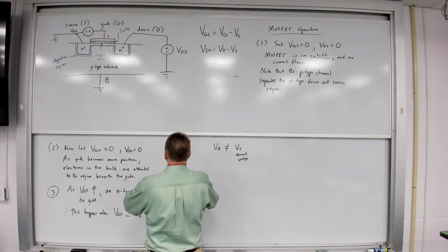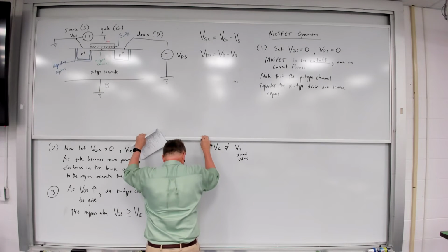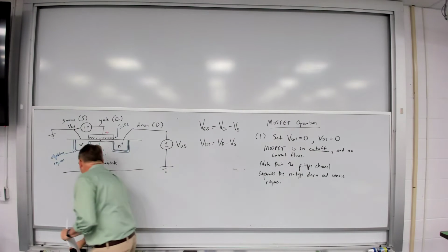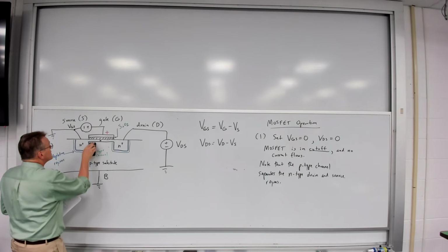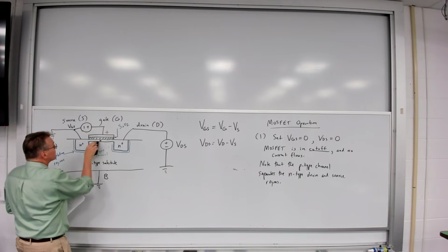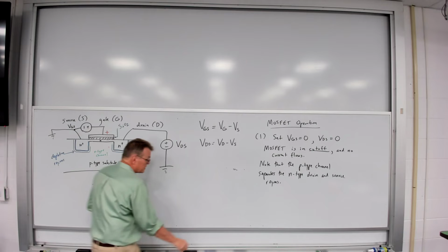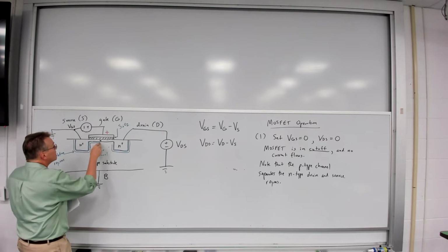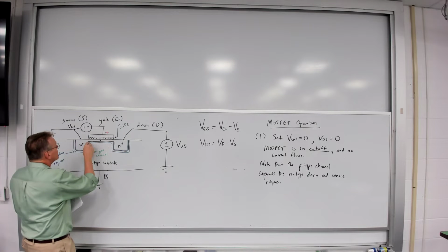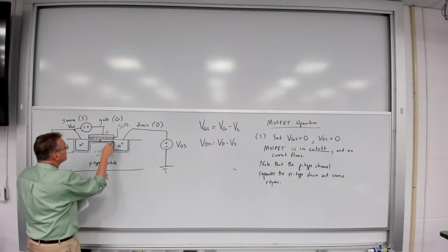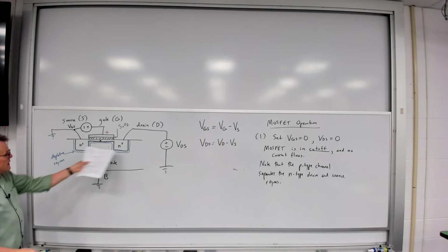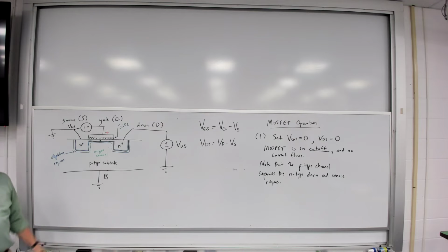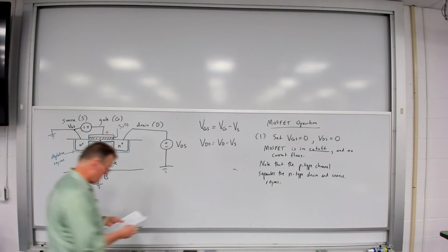Okay, so once this happens, and this region is formed, what I'm going to see is now this depletion region is going to extend all the way around. So now my depletion region goes all through the channel, connecting the drain and the source together. So now there is a path between the drain and the source, thanks to that channel. Okay?